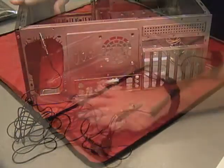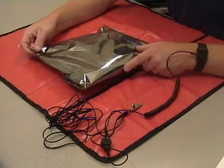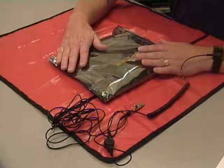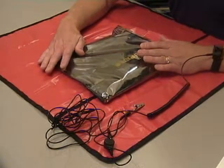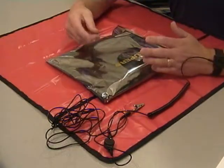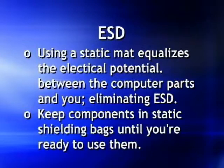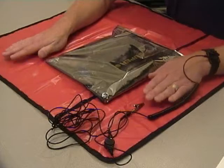Now, when you are working with electrical components that go inside your computer, they are shipped to you in these mylar bags. These may appear to be just typical regular old mylar bags. They're not. These are static shielding bags, because they are designed to dissipate any charge that might accidentally hit them through an electrostatic discharge. Rule of thumb is, whenever you're dealing with a component, always keep it inside of a static bag until you're ready to use it, and make sure you're working on top of a static mat. With that, we're actually ready now to start building the system. All right, let's go.